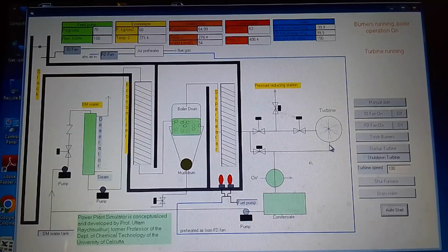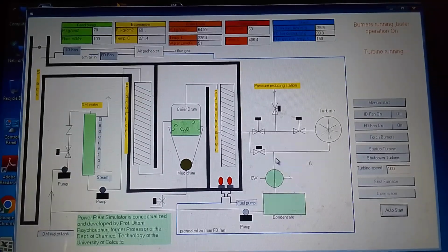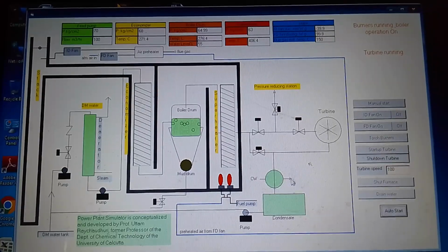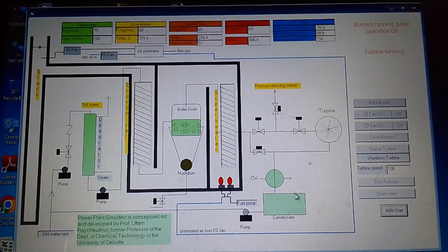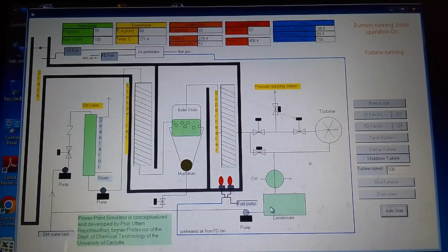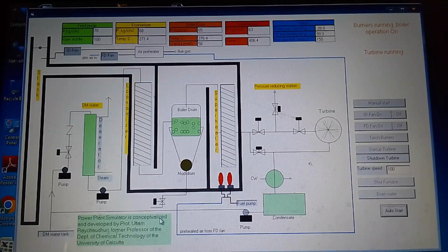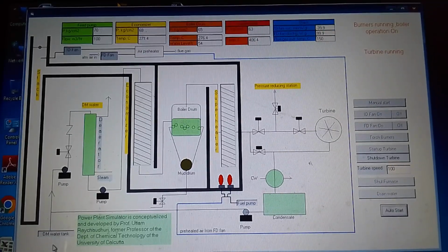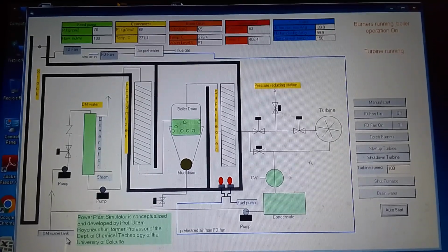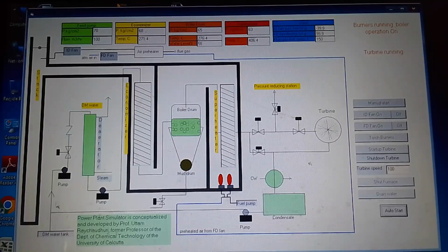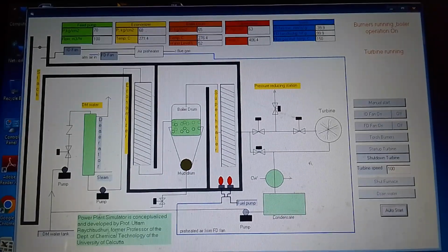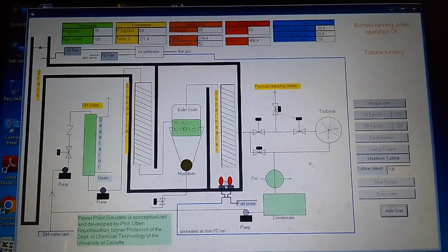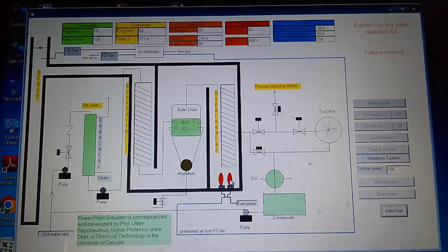Now the steam which is condensed is returned to the cooling water with the help of this condenser, and then to this steam recovery section, where all these condensates are mostly returned back and recycled, because it's DM water, which is valuable as demineralized water. So this is a general description of a water tube boiler. As I showed you, gas or liquid firing or combination firing is possible. The maximum temperature occurs in the superheater.